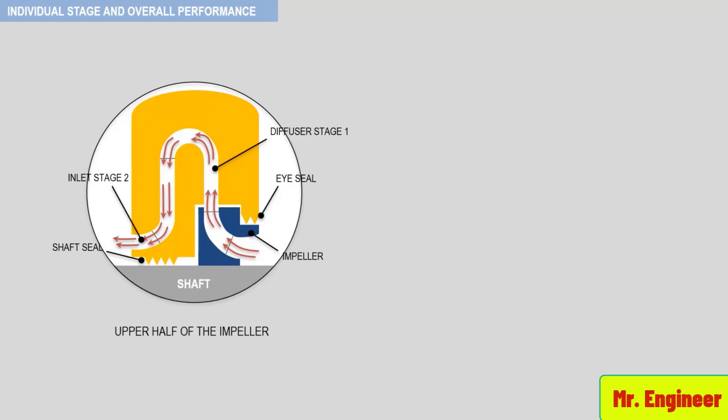For each impeller or blade stage, there exists a specific performance curve. In order to achieve maximum efficiency and flow range in a multi-stage dynamic compressor, each stage should be operating at its maximum efficiency point when the compressor is at its rated point. This is not true for many older designs where only a limited number of compressor impeller or blade designs were available to select from.